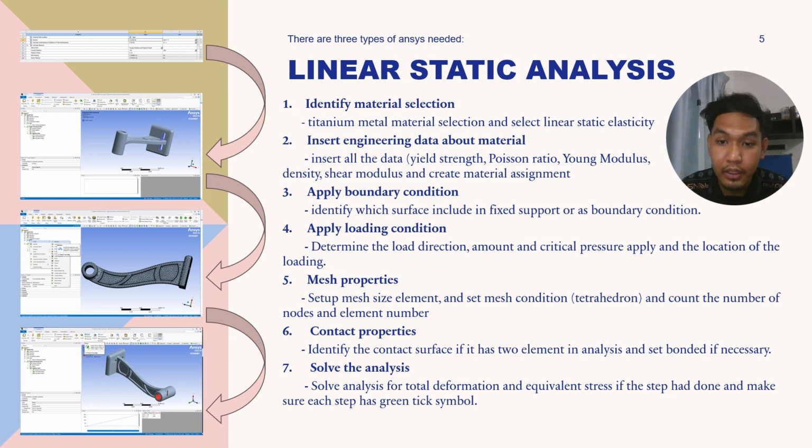Select the inner two face bodies as convection types and magnitude 300 Newton as the load shown above, and then click apply to the selected body until it turns red. The direction of the force load is downwards in the z-axis position, and the surface effect was applied.